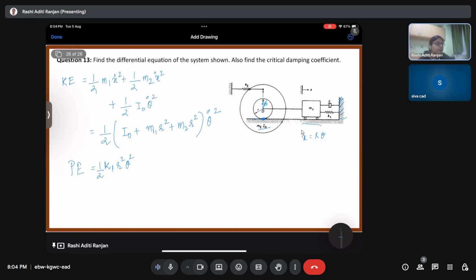See, that is how we work with the no slipping condition. If the center had been fixed, we would have rotated in terms of a. But here we are considering this point. The rotation is actually happening about this point, right? So how do we now write the displacement? If you see clearly how it is happening, first, the center is moving by x. It is clear to us that the center of this pulley is moving by x.